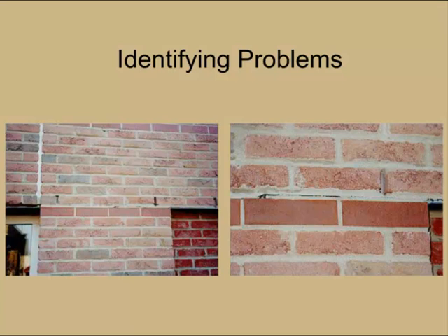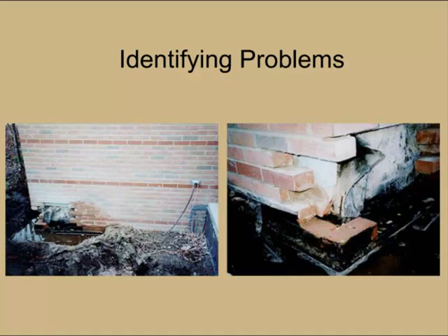Good. Next here, we've got a through-wall embedded flashing that's coming out of the wall system. Great design. Problem is we have poor workmanship, poor execution. That was covered with mortar, which made the flashing ineffective. It trapped the water inside the system. Good design, poor workmanship. This is an example of good design that wasn't carried far enough. If you look close, you can see that there was proper flashing in there, but there was no end dam condition, which led to failure of the brick.